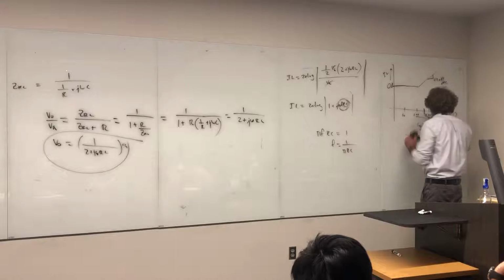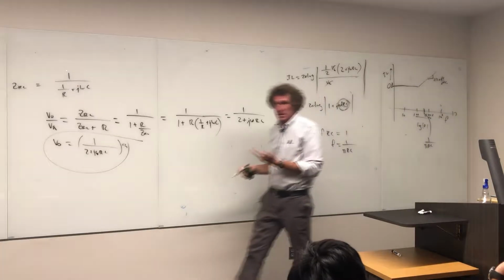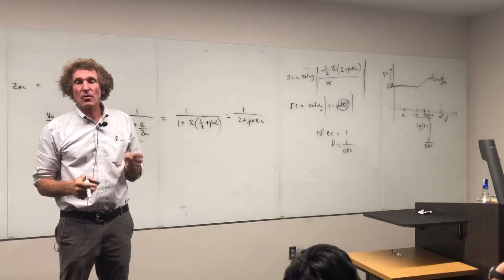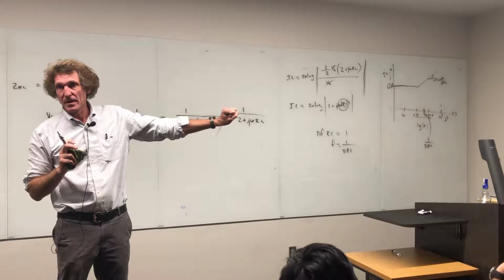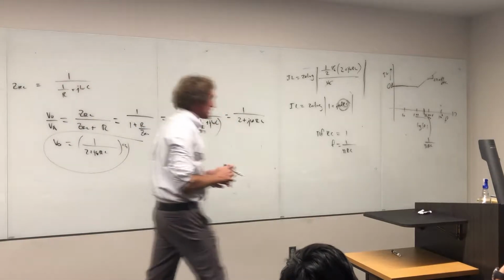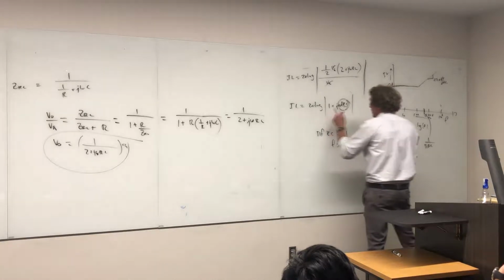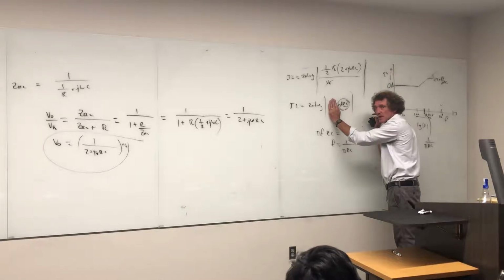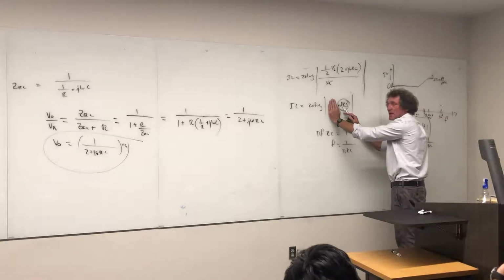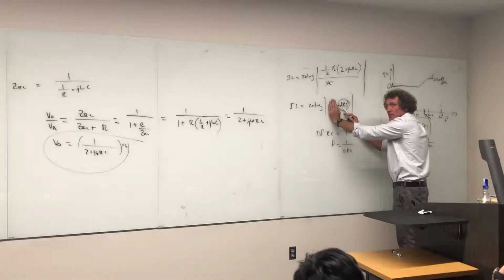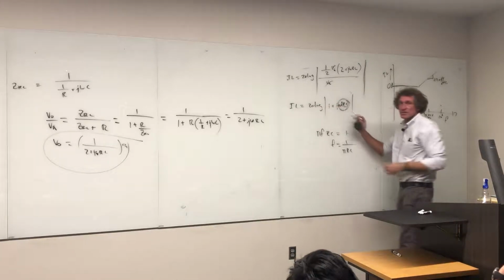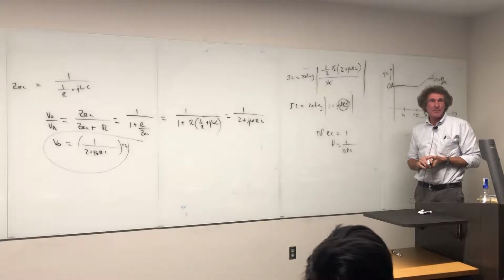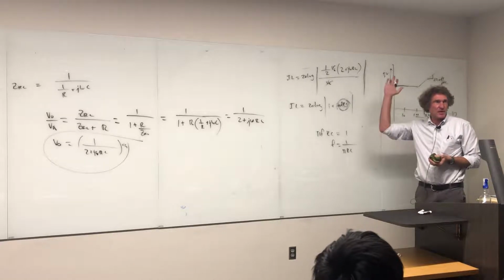Do you all see that? It's going to start rising at that rate, correct, class? Because now omega, or really pi f times RC, is greater than 1, and that dominates. You can just figure this out. When you're an order of magnitude greater than 1, really it's the log of just pi f RC, right? And every time you go up by a factor of 10 in frequency, you bring out 1 extra 20. So it's 20 dB per decade. Can you all understand that, class? Everybody? It's hard to see back there. Give me a show of hands if you are with me.